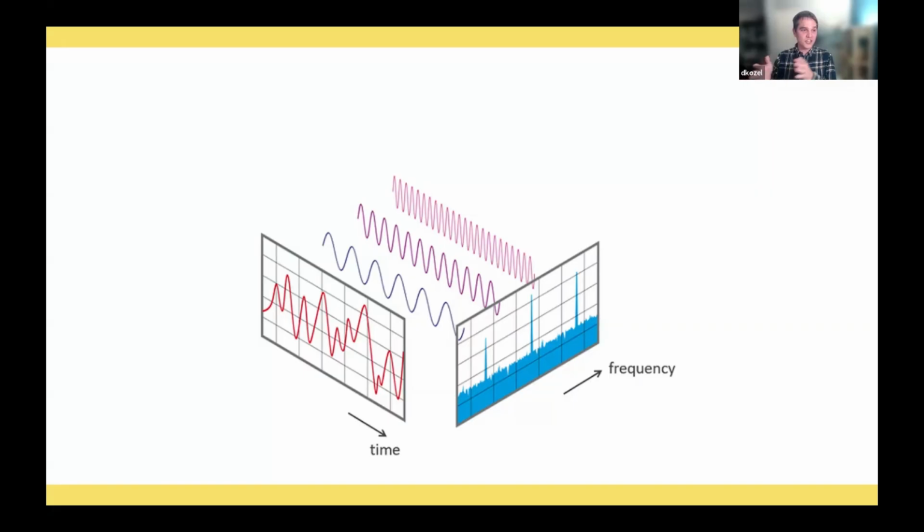Where is the energy? What frequency is there energy at in this amount of time that I've measured? And so we have a time domain signal and we can transfer it into a frequency domain plot. Derek, my VNA is only measuring in the frequency domain. Yes, and it's measuring power and phase. We have a complex power measurement here, which is what the Fourier transform puts out.